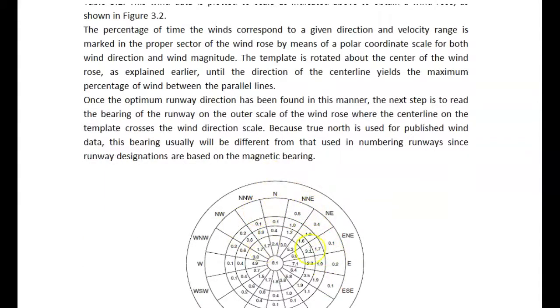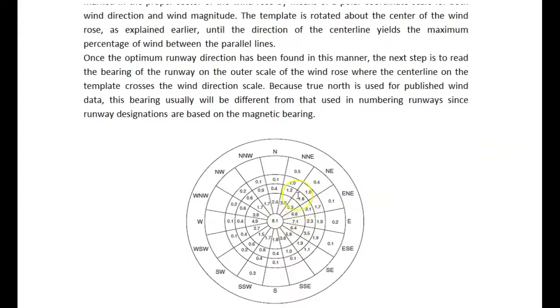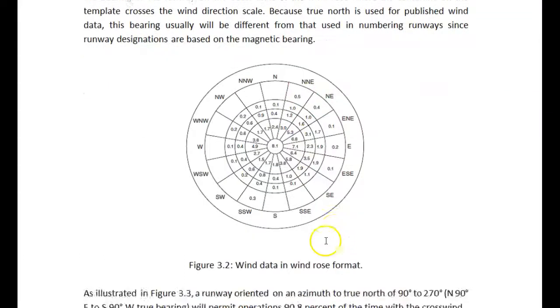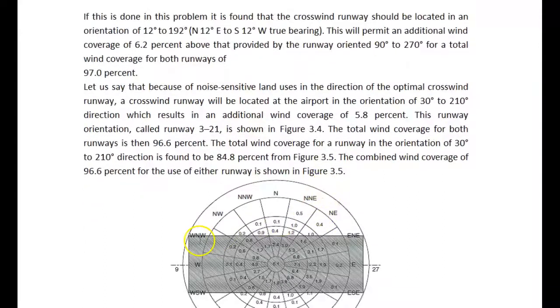the wind rose until we're able to determine where the largest amount of wind blows. So if we're able to get it from one attempt, from one sector represented by the template, or from several sectors covered by the template, just as we have here, you can see these are various sectors that fall in between, because this now shows a runway.